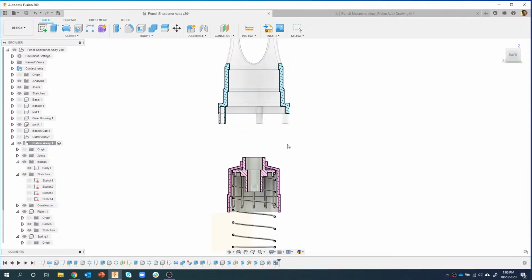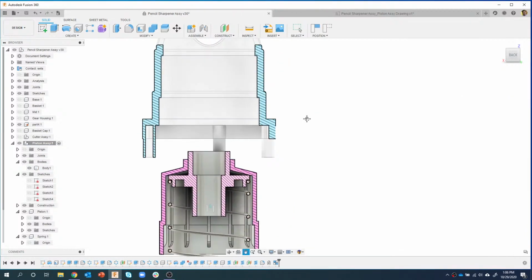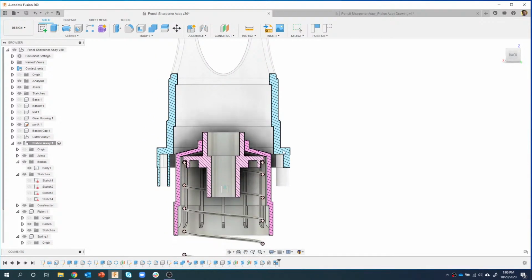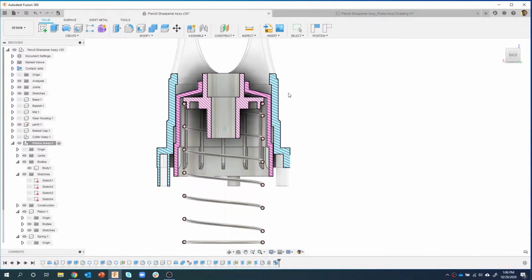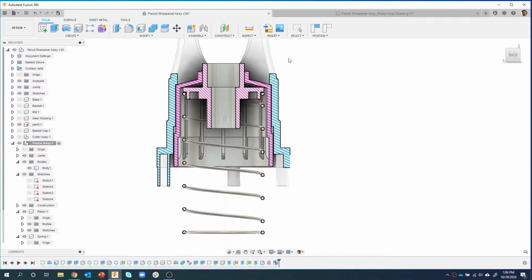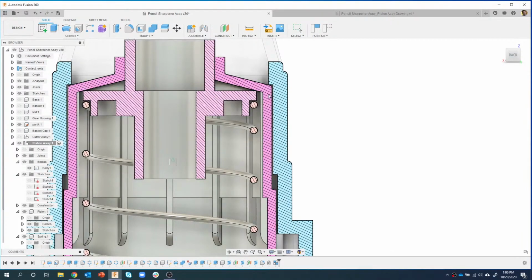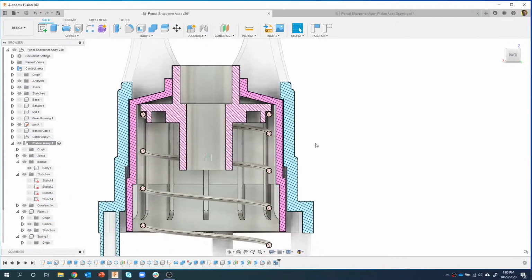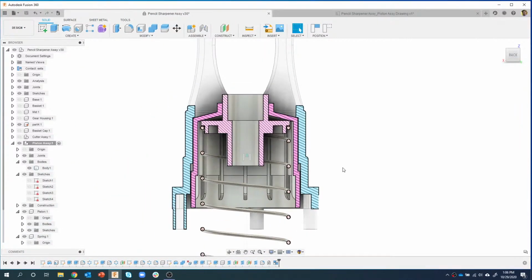Okay, so let me just drag this up a little bit, kind of zoom up here, drag this up. I'm going to keep moving up. Everything's great so far, and then you see, even though I'm still moving up, it stops. And that is because of right here. So you can see how it's intersecting at that corner right there. So we've physically positioned this assembly inside this other assembly. Okay. I'll go ahead and capture that position.